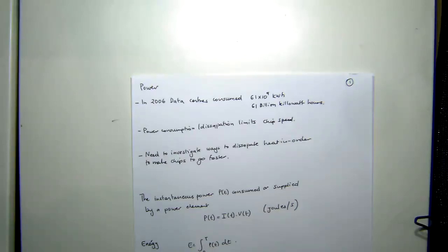It does affect it, but essentially the way that you build chips is you implant and you anneal in order to have those tubs. Remember, for example, if you had an NMOS transistor. Now, there are two issues, right? The first is as temperature increases, the performance of your transistor decreases. It usually goes as T to the minus 3 on 2, which means that your gain and the like decreases.